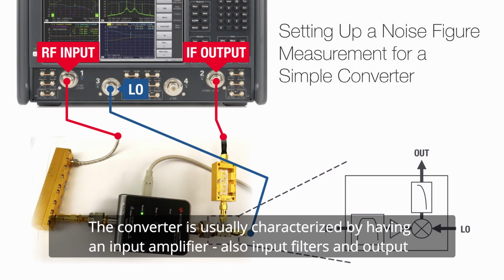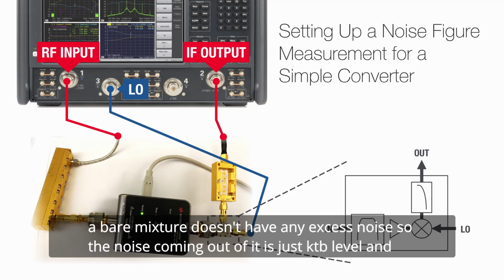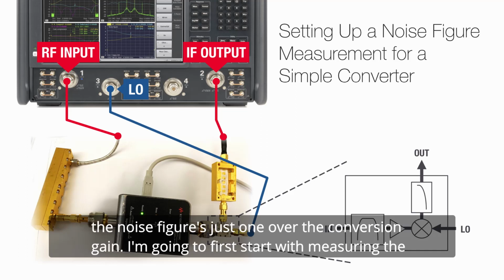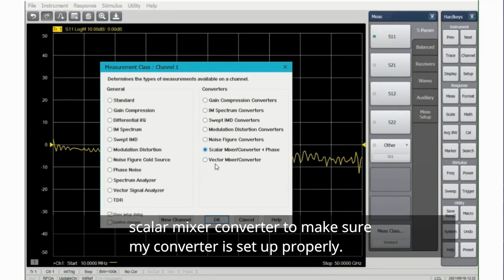A converter is usually characterized by having an input amplifier, also input filters and output filters. A bare mixer is something we usually don't measure the noise figure on, because a bare mixer doesn't have any excess noise, so the noise coming out of it is just KTB level, and the noise figure is just 1 over the conversion gain. I'm going to first start with measuring the scalar mixer converter to make sure my converter is set up properly.